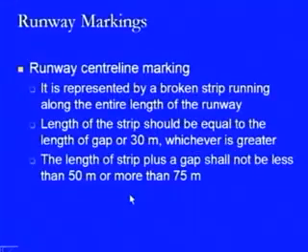The length of the strip plus a gap shall not be less than 50 meters or more than 75 meters. So, in this sense, if we look at the previous one, where the strip should be equal to the length of the gap or 30 meters, whichever is greater, and if we assume 30 meters is the greater value, then the gap is going to be 20 meters if we take the value of 50 meters.